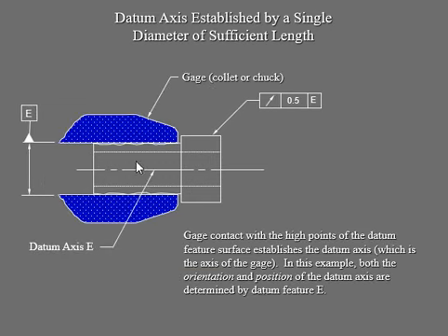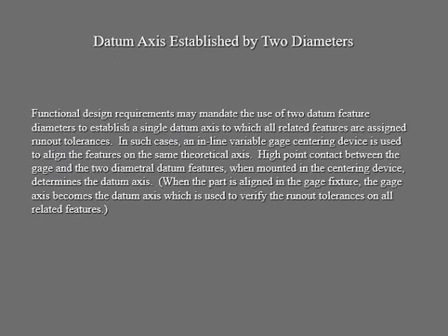So we can see orientation, also the position of that datum axis established by that datum feature, which is your E. And we can get this datum axis E, established by this datum feature E. Okay, so here is your gauge, and this is your circular runout, and that's a 0.5 based on the datum feature E, which is your datum reference anyway.